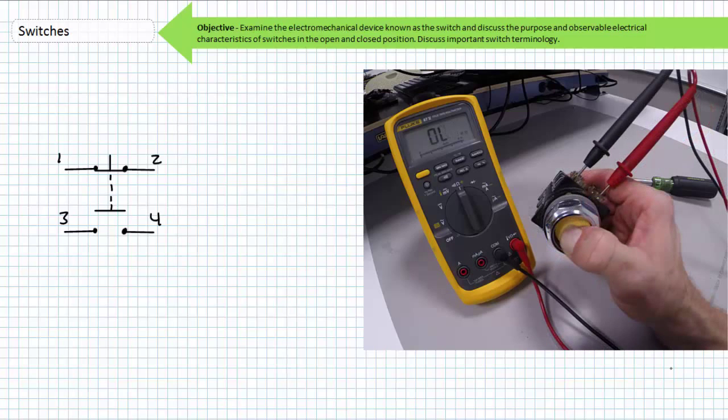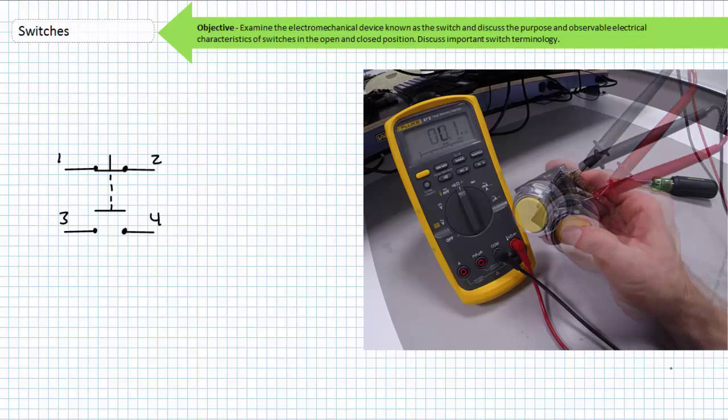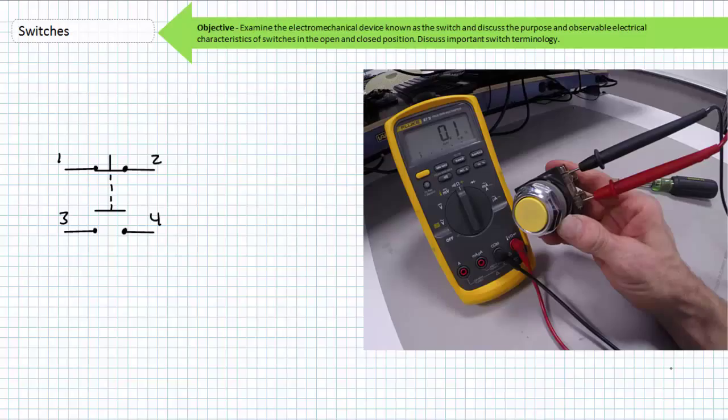When the button is actuated, the ohm meter indicates an open from 1 to 2. It makes sense. A normally closed switch opens up when you actuate it. This switch is behaving exactly like the first switch on the emergency stop button, but with one important distinction. When I release my thumb from the button, the ohm meter indicates the spring-loaded push button has returned to its deactivated state of closed. This is a momentary switch. Only when I actuate it will these switches be in their activated state.